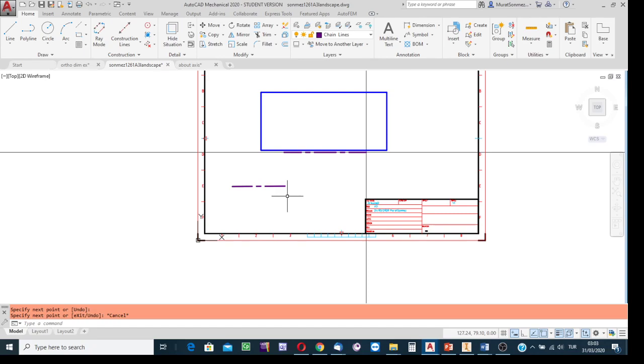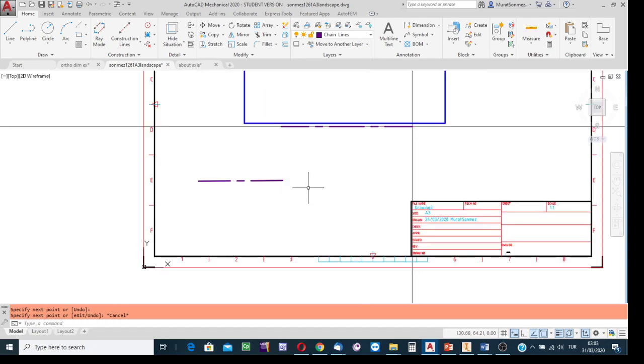Having a look at the created chain lines, I see that the order of the dashes in length is not so good. Along the line of action, having only one or two dashes is a poor practice. To draw the attention of the reader that it is such an interrupted line, have more dashes.